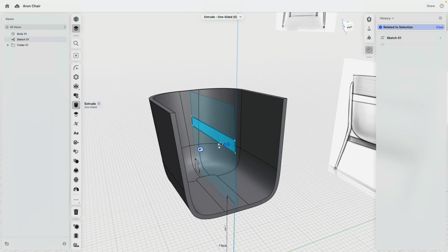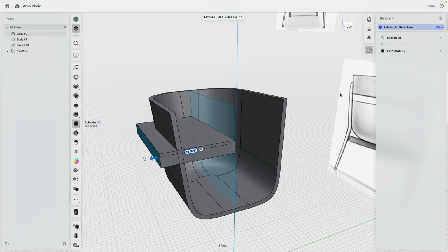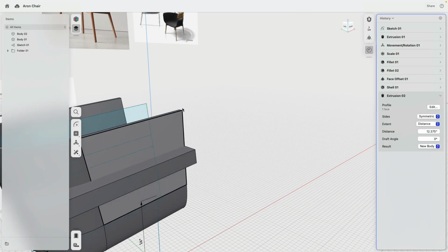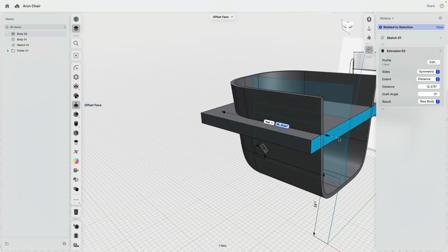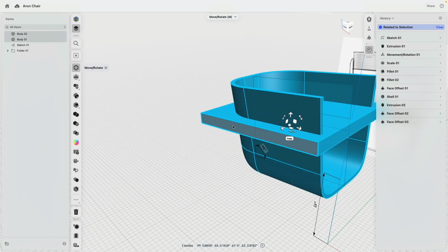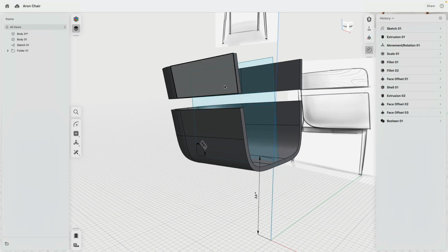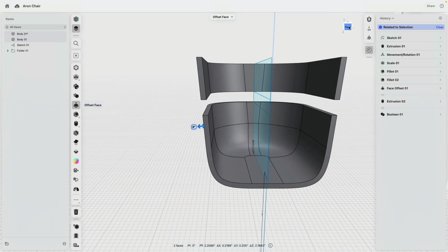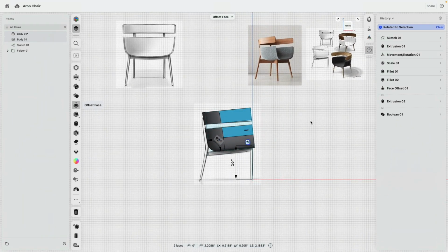And then here, this piece, how do we do this? I will extrude this both directions. I'm overbuilding this, making this bigger than necessary. And then from this, I will remove that one, subtract. And now you see, I have a perfect flow of surfaces. That's pretty good. Okay, beautiful.